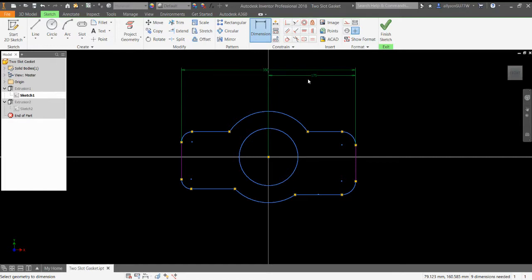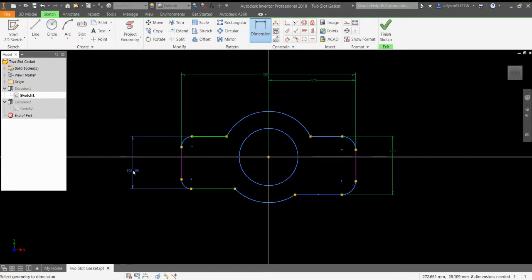And then the other dimension that I want to put is, it's actually not this line, it's the overall width of this. The overall width should be 120 millimeters. Okay, so I have pretty much the overall basic starting dimensions to go with. So let's make sure that this is the same on this side, because this should also be 120. So now we fix that.